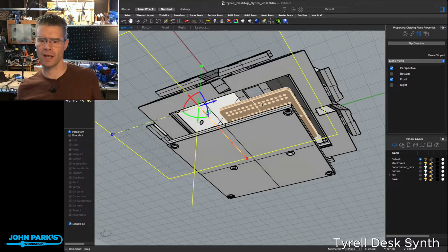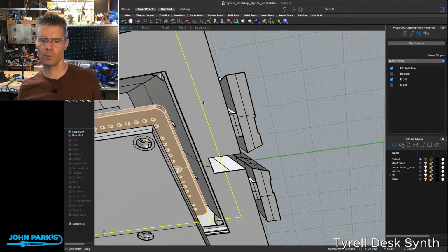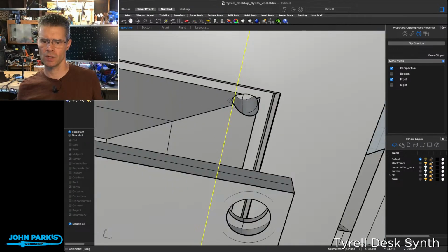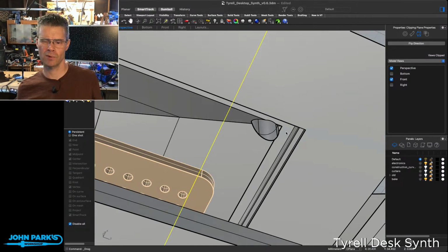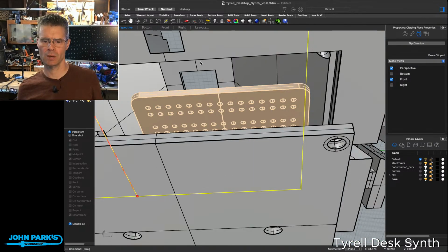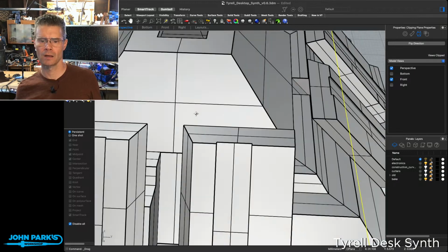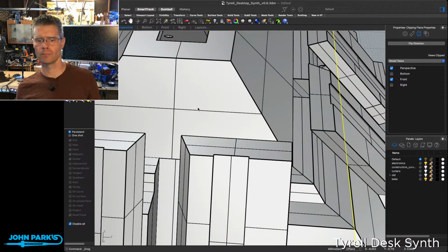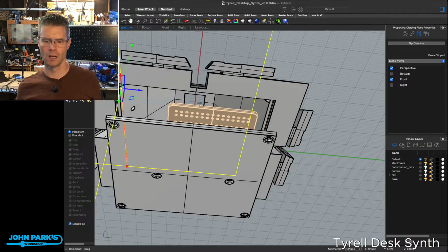But I think now that I have this lip here for putting the base in, you kind of want that to be neat. So printing it with support helps that. You don't really need the one up in the chimney there, but mine printed with a little column, a little chimney going up to there. That's okay if that's rough on the bottom since you won't see it.